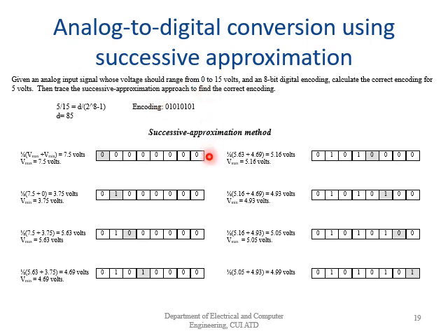In successive approximation, we start from the middle. So choose a common point. How can we start from the middle? V max plus V min, where V max is 15 and V min is 0, divided by 2. So it becomes 7.5. You can see that 7.5 is greater than our target, that is 5.